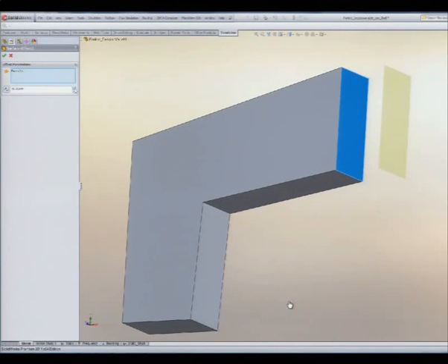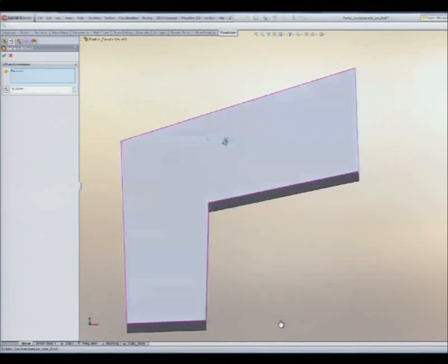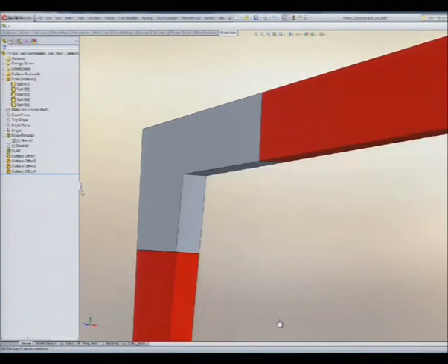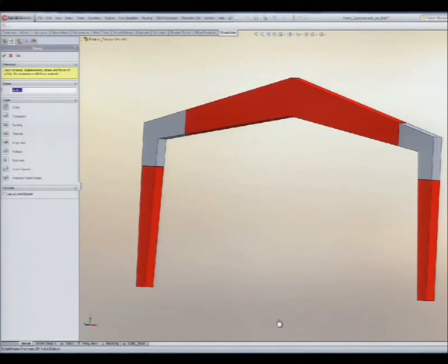Why? Because if I don't have this rigid surface, the problem is that the beam will produce a rotation only of some nodes of the solid. So what I actually get is a softer model than the real model. Is that clear? Okay. So this is the trick: put in a rigid surface. In SolidWorks, I have to right-click, treat as rigid.